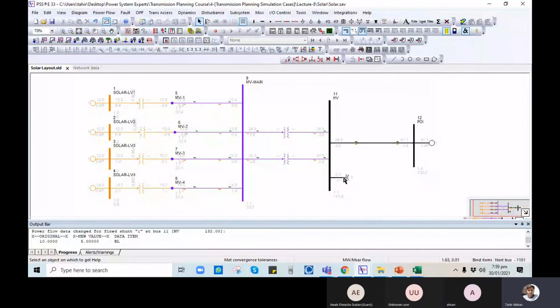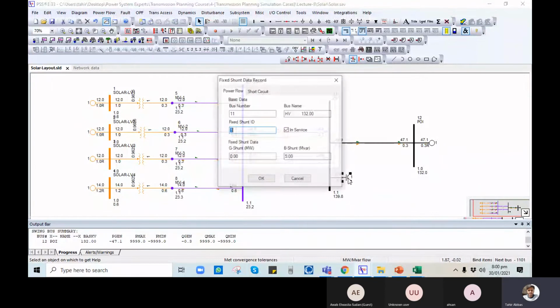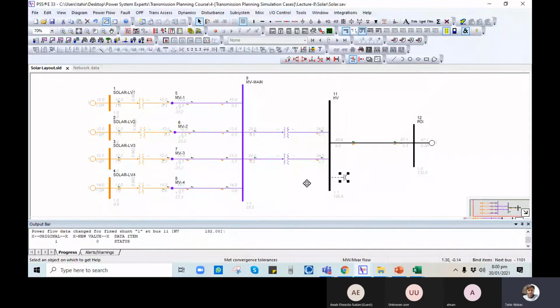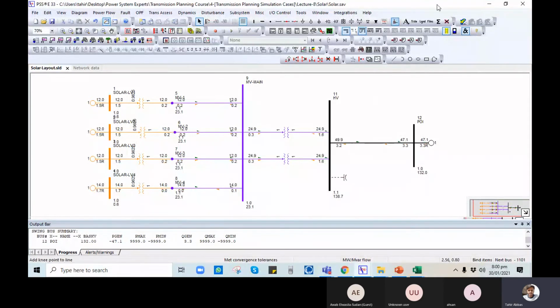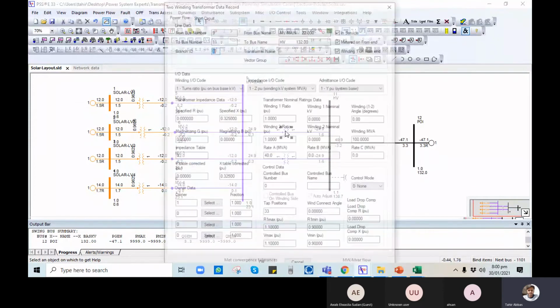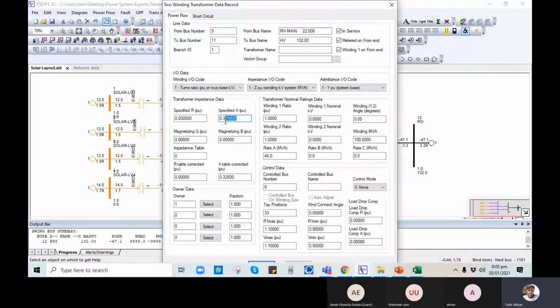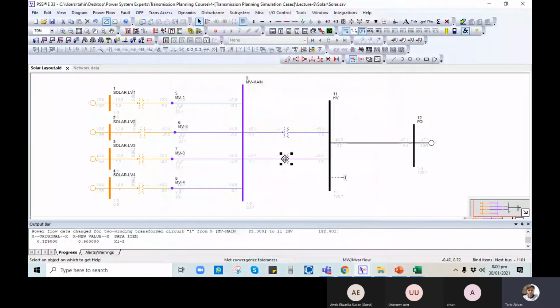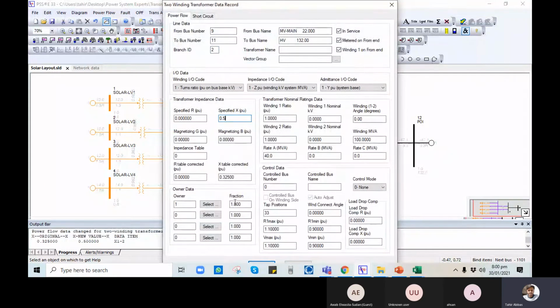Yes, it's already high, therefore we can switch it off, simple. But I want to explain that we can control this reactive power from this plant. So why is it high? Only due to this reactance. If we are adding this much reactance, 0.5, then we are not following the proper design, right? We are just adding data based on the calculation.